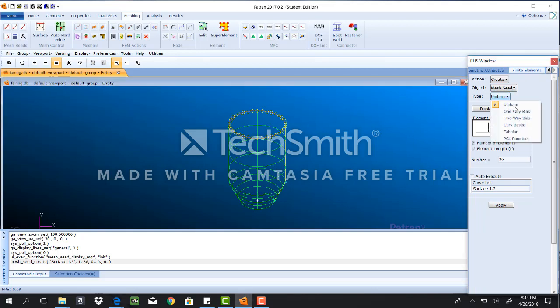After that, we are going to go for create mesh set and one-way bias. We select the L1 and L2. L1 of number 7 and L2 equals to 10. In the curve list, we're going to select the curve 1. And then apply it.